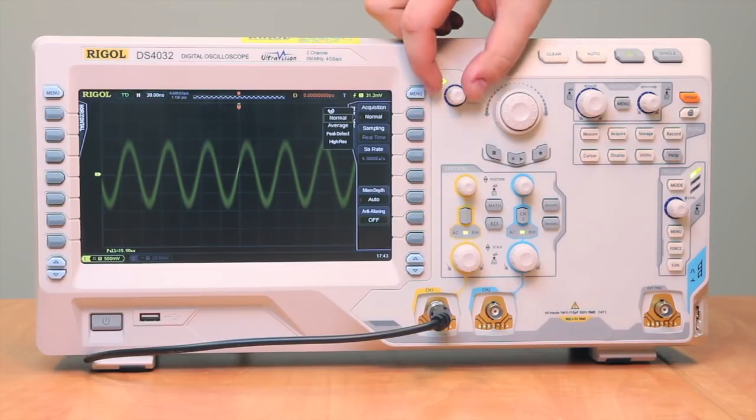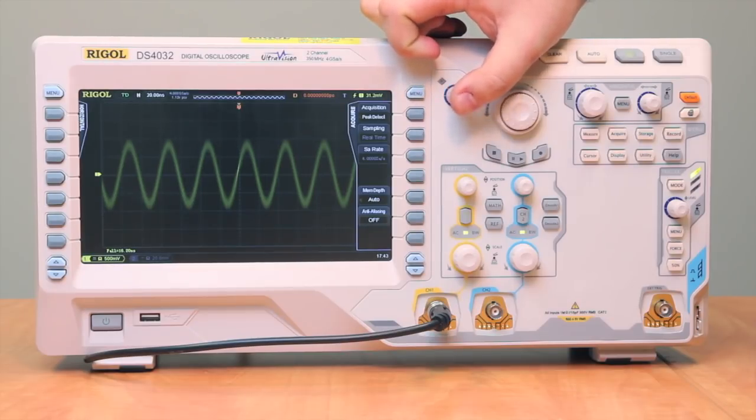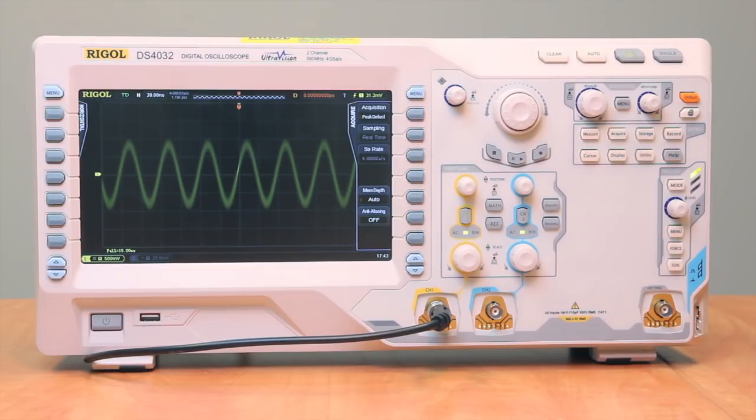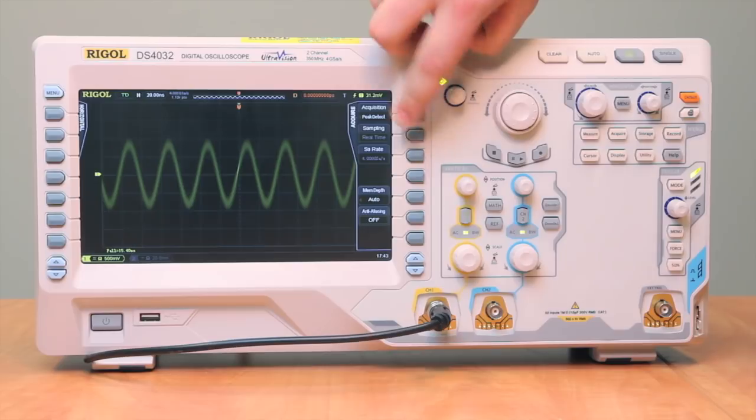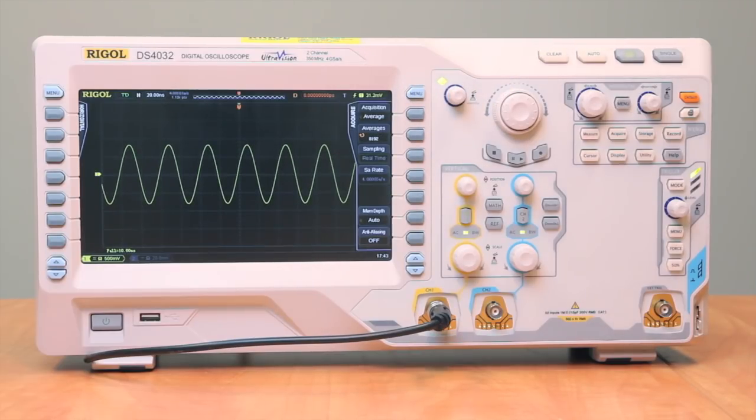The peak detect mode for a signal like this looks a lot like the normal, but in essence the peak detect just accentuates some outliers, so it can help you find errors that way. And then average does something interesting. What average does is it takes successive captures and overlays them and averages them together. So at points the same distance from the trigger point, it will average together to reduce the overall system noise.